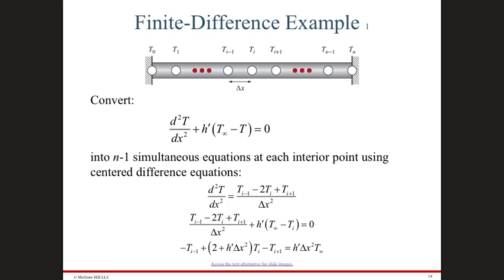So you can imagine that if you write the matrix that represents those set, the equations are going to be for T0, so T at location 0, T1, T2, T3, T4, until you reach whatever. So let's say the 10 meter, you are going to divide that into centimeters. This means that you will have 1,000 T's. Each one of them is a function of the next one and the previous one. And for the first one, the initial condition defines it. For the last one, the boundary condition defines it.